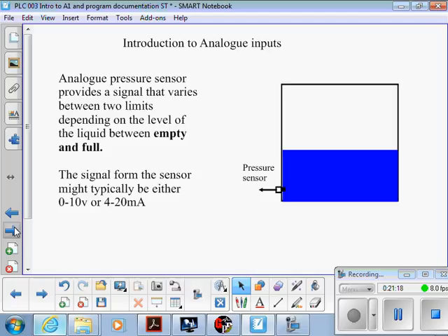Your Mitsubishi PLC, certainly the FX models, we've got some analog boards, and they will take either 0 to 5, 0 to 10 volt, or 4 to 20 milliamp signals, selectable in software. So it depends how you program the setup of that analog card as to what type of signal it's going to take. And how you wire it, of course.